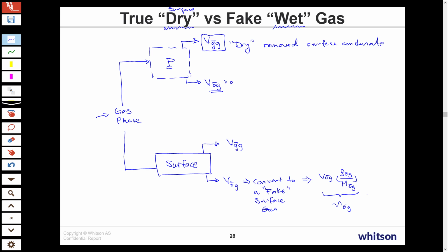And then we use that molar quantity and multiply that by the conversion from moles to standard cubic feet of gas. Well, the conversion from the ideal gas law of any number of moles. This is from the ideal gas law. If you just say you've got some moles of something and it's going to be created or considered as an ideal gas, then this term here will be R standard temperature over standard pressure. That's the equation.